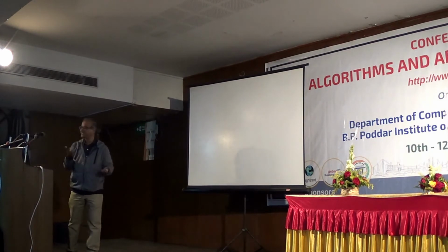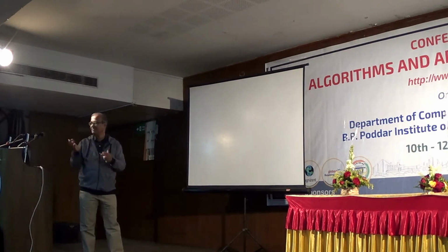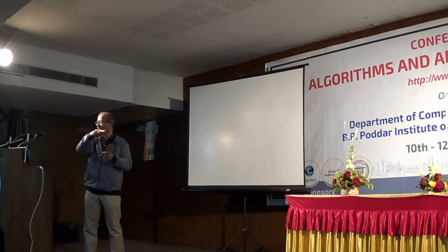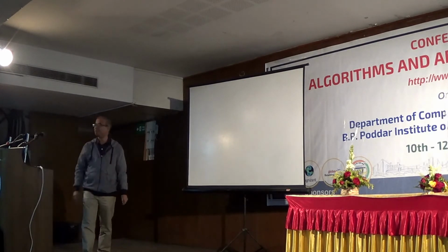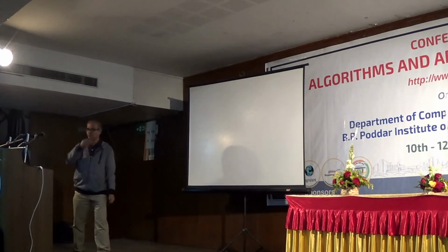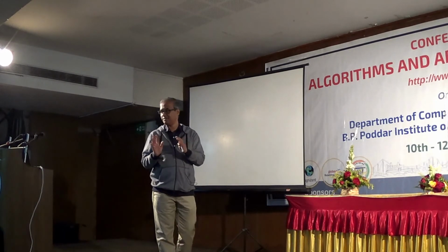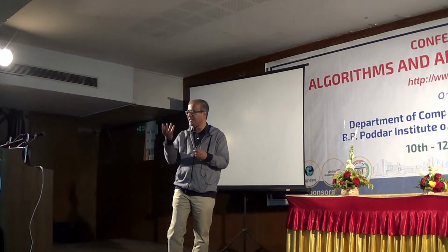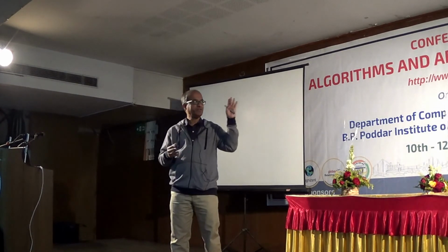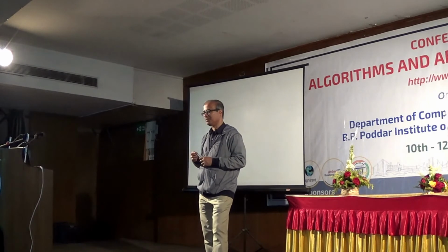So you will be sensing a high current. This is called the sneak path problem. Whenever you are using memristors in memory, or any application where you want to read the value of the memristors, you should be aware of the sneak path problem.